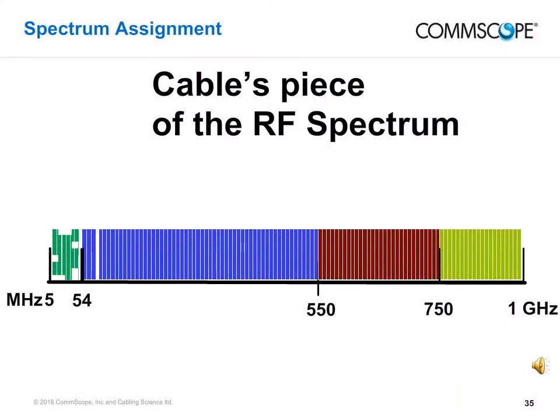To avoid conflicts and interference, frequencies within the RF spectrum are managed and assigned by governmental agencies within each country. In the U.S., cable telecommunications has been assigned the RF frequency spectrum from 54 MHz to 1 GHz to send signals to its subscribers. This group of frequencies is called downstream. In addition to these downstream frequencies, there is also a set of frequencies dedicated to upstream transmission from subscribers. In the U.S., this band is from 5 to 42 MHz.